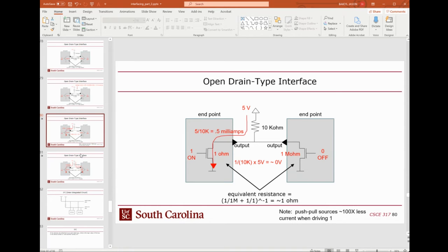So this type of connection would be basically logic 1 all the time when no device is sending a bit. And then each of the drivers would only have to worry about setting it to 0 at the appropriate time. The problem is that if two devices send 0 at the same time, it's hard to tell that there's a conflict. So the only way to solve that is through the protocol.